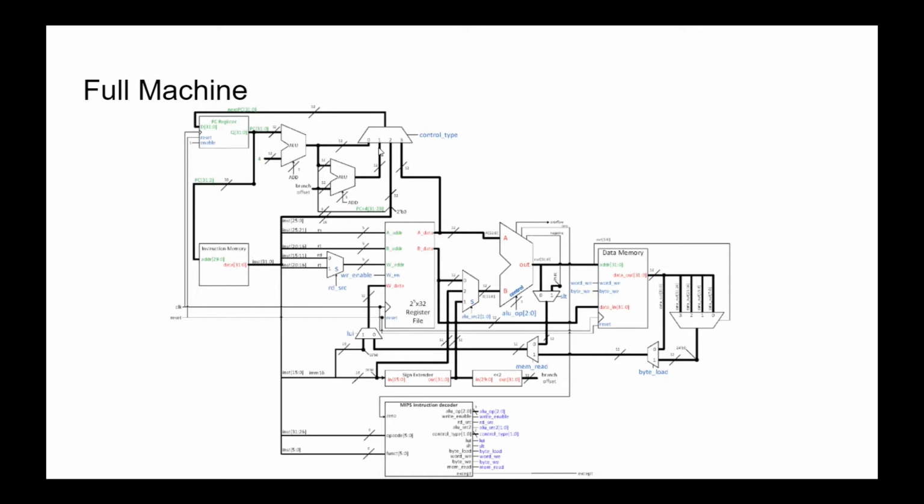Now, branches, as I think we've discussed before, are what are called relative jump instructions, which means that the address of the next instruction is given by some part of the instruction itself added to the program counter. And so, in the case of MIPS, the branch instructions have a 16-bit immediate in their immediate field. This is down here. And what we do is we take that immediate, we use it as an offset from the current instruction to figure out what the next instruction is going to be, and we treat it as a signed number.